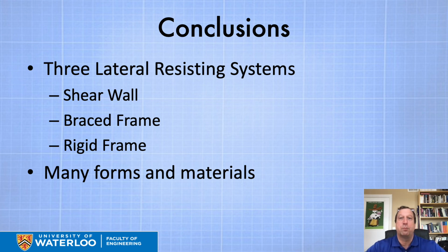Just keep your mind open to the possibility that they exist, and understand that in any building structure, you're going to have to find out: how does the diaphragm work? What are the lateral load resisting systems? How do the side loads get down to the ground?